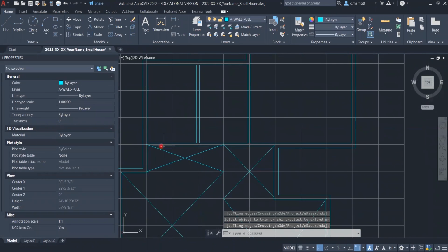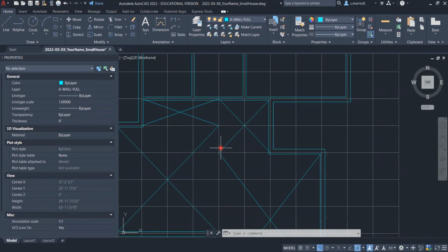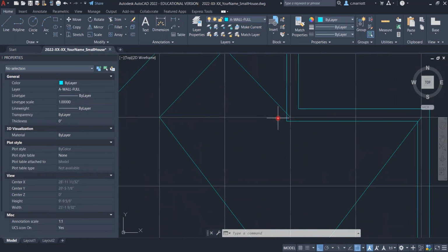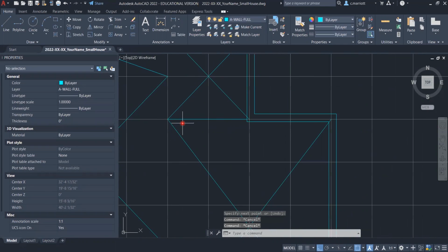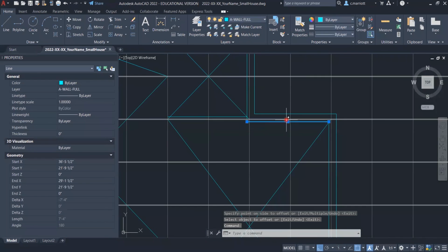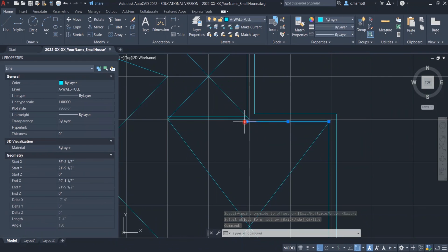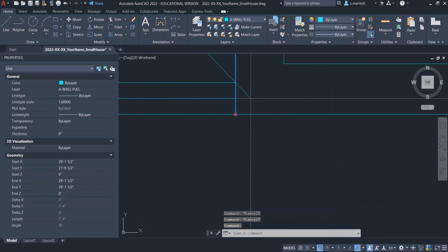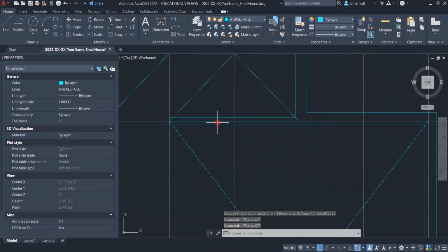Now, right now, I'm just enclosing these entirely. At some point, I will create openings and doorways and things like that. At the moment, I'm just going to block most of the walls in. I'm going to make a line down the middle here. This is my vestibule. Offset 2.5. Okay, this one is going to extend. So instead of having two lines that kind of join, it's better typically to extend them all the way. We can go in and start to clean up intersections too.